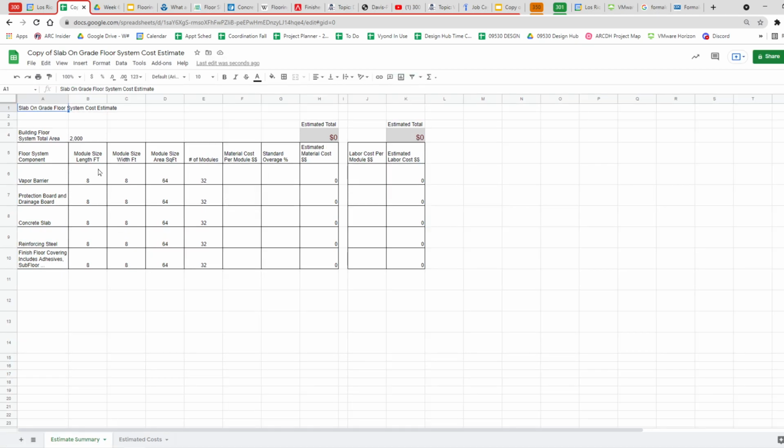And this is that idea about modules again. I've got 2,000 square feet, and I know that if I design by 8 foot by 8 foot, I can mix and match little 8-foot squares into most buildings, and I'll waste a little bit here, and I'll need a little bit extra there, and I'll be okay if I do that.